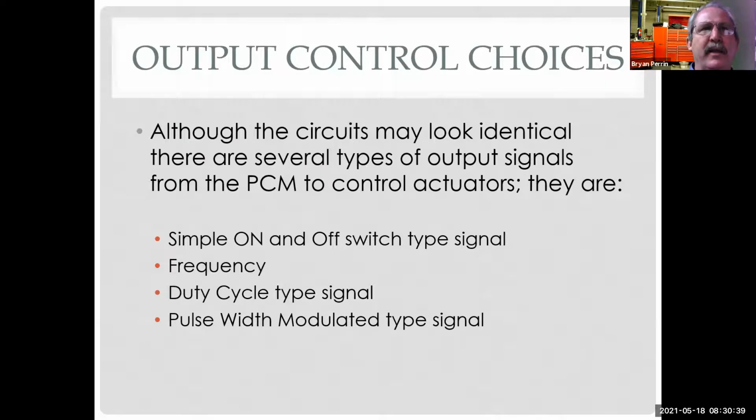So I think it's more about protecting the system durability and control than it is about measuring current. Now, the byproduct of that is because of all that control, they are able to measure current. So we see a lot more data PIDs on a scan tool for current now than we used to, because the computers are seeing that, where before they just saw voltage. But I think that's a byproduct of the technology, not the reason for it.